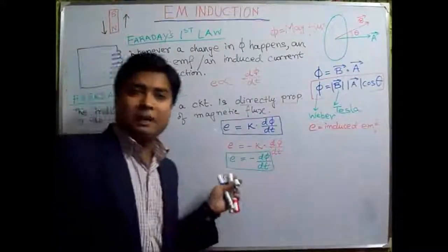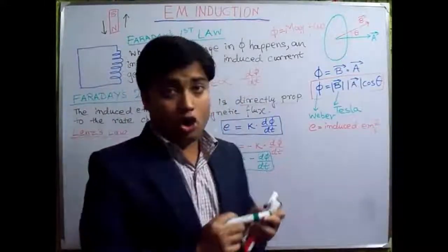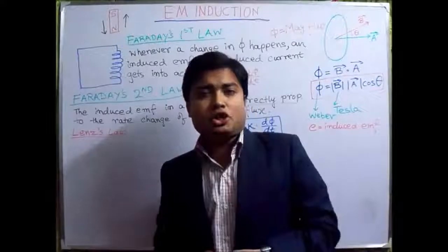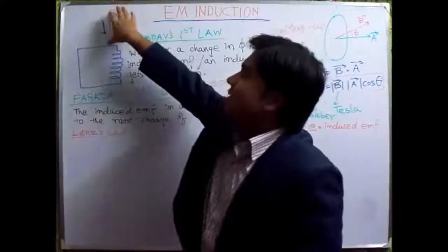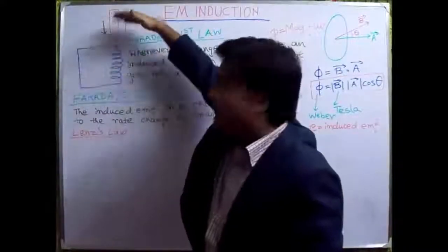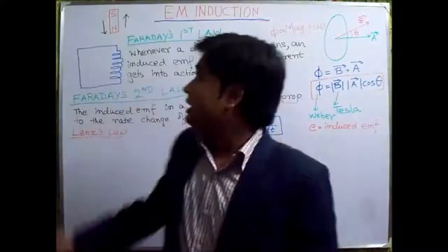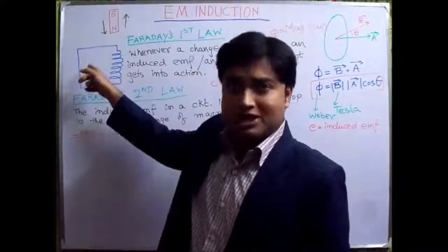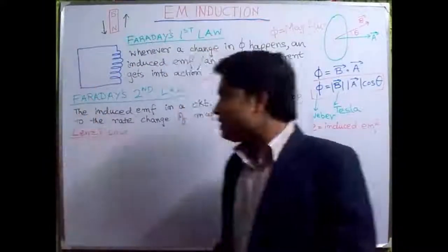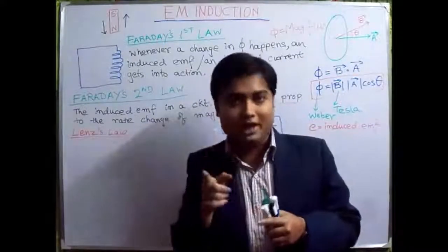So this is the expression for the induced EMF, which is in accordance with Faraday's laws as well as the Lenz law. Now in the Lenz law, this mechanical energy is needed because we have to move this bar magnet so as to produce a change in this magnetic flux, and then the current will be induced within this circuit. So the mechanical energy is now getting converted into electrical energy. So this Lenz law is in accordance with the law of conservation of energy, right?